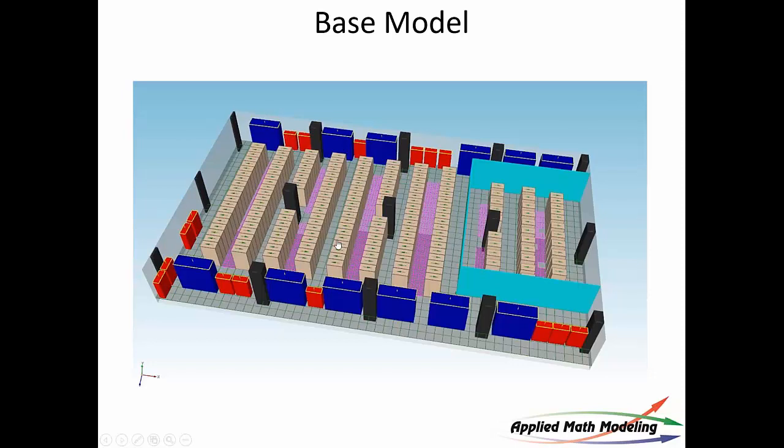The arrows indicate airflow direction, so you can see it's cold here and hot over here, and very natural. The only reason there's partitions around this is probably a colo. These are screens with a high percent open area, so they're not enclosed. This is all open from an airflow point of view. Very common, and PDUs are in red around the perimeter. Very common data center. That's not unusual here.